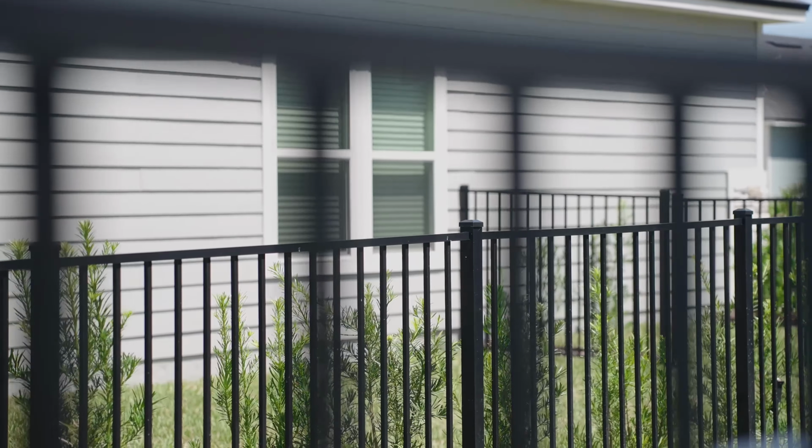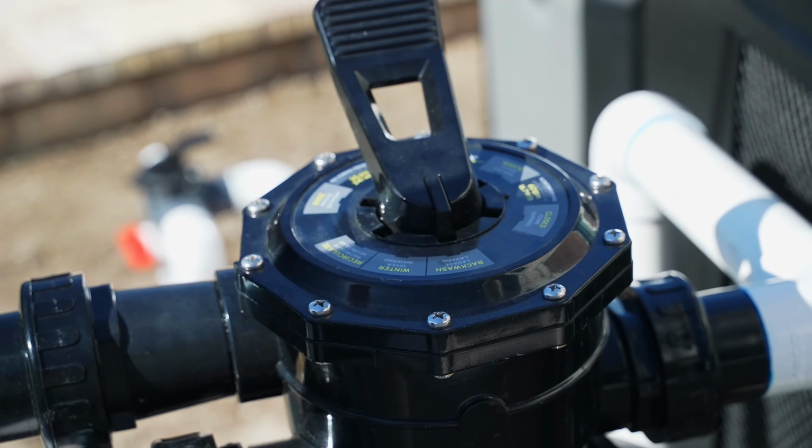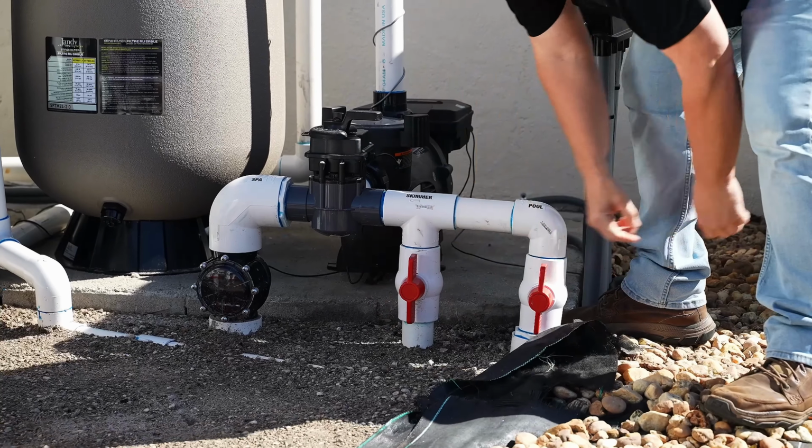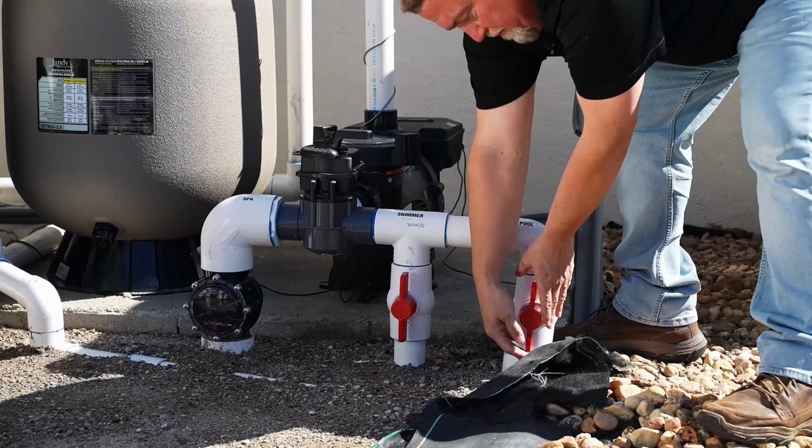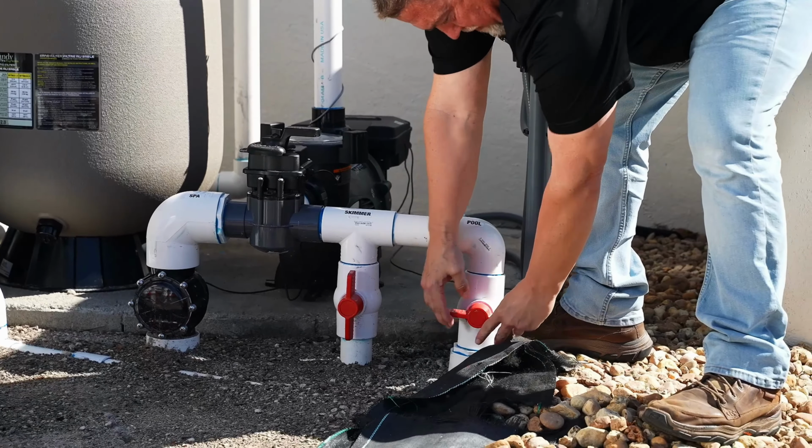A lot of the pools that we construct and a lot of pools that are currently being built have automation attached to them. With that automation, there's automatic valves called actuators. To properly turn the actuator, you cannot manually turn it. You have to use the toggle switch at the bottom left corner that will rotate the valve manually. By doing that, flip the toggle switch into the opposite position that it's currently in. The valve will rotate, and that will allow you to get more suction through your skimmer and isolate your main drain.